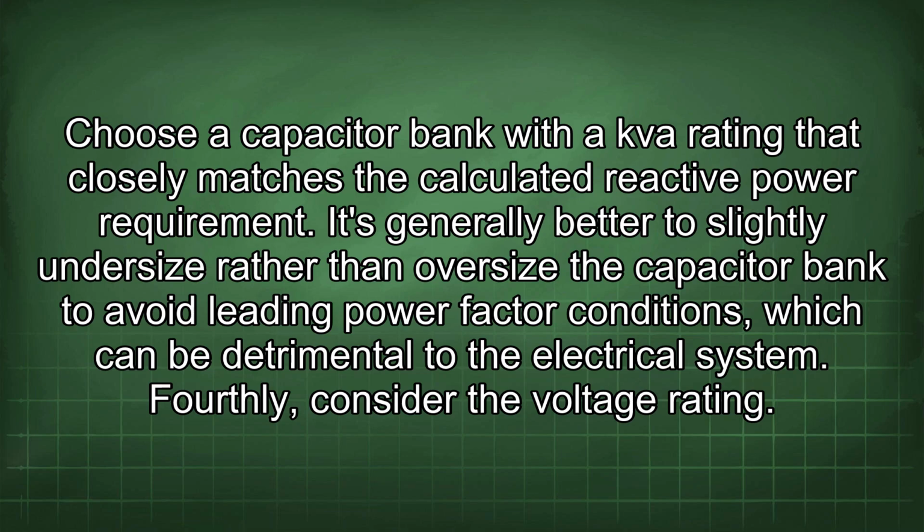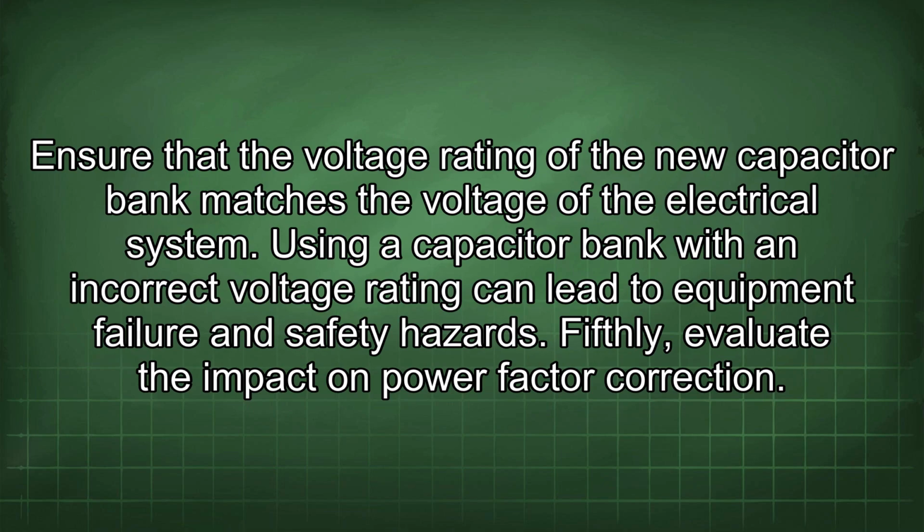Fourthly, consider the voltage rating. Ensure that the voltage rating of the new capacitor bank matches the voltage of the electrical system. Using a capacitor bank with an incorrect voltage rating can lead to equipment failure and safety hazards.